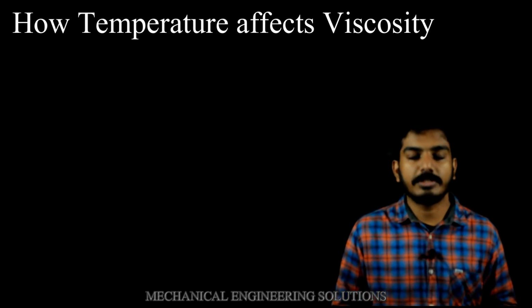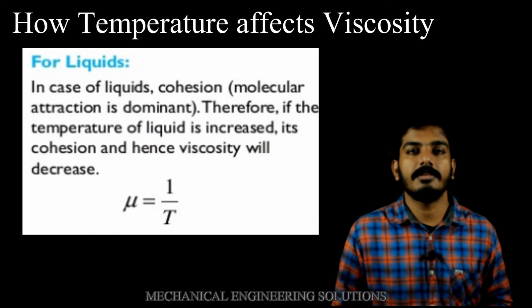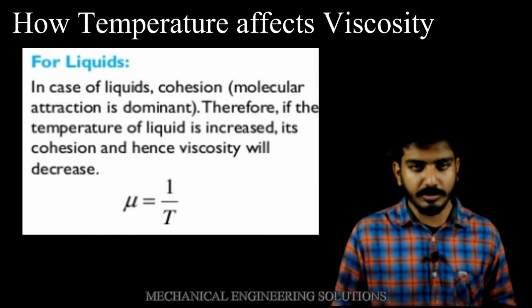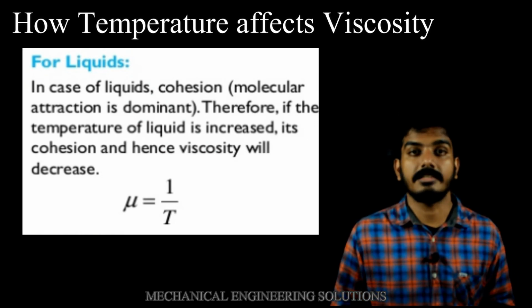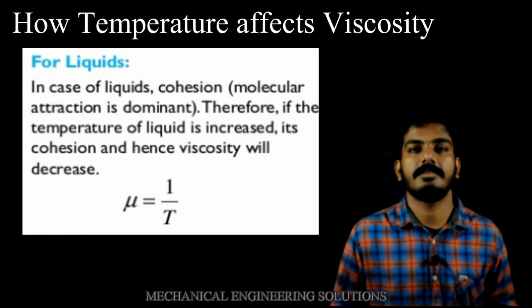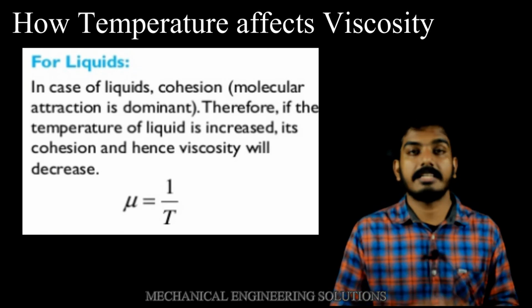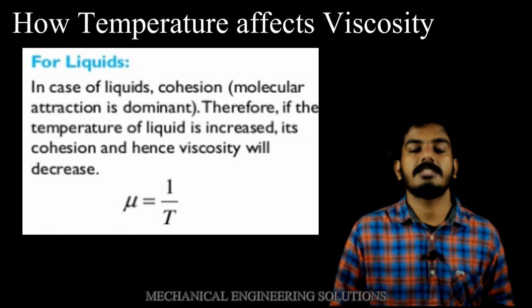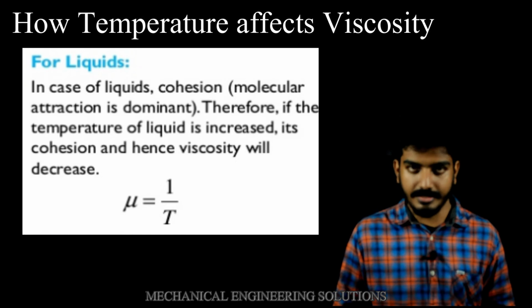In liquids, the viscosity is due to the cohesive force between adjacent molecules. When the temperature increases, the intermolecular spacing also increases. As a result, the cohesive force decreases. This results in a reduction in viscosity. So we can conclude that in liquids, as the temperature increases, the viscosity decreases.